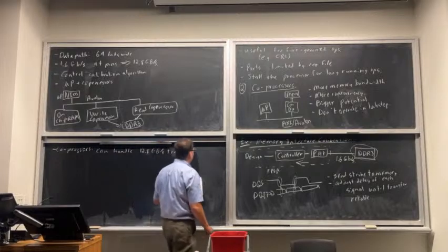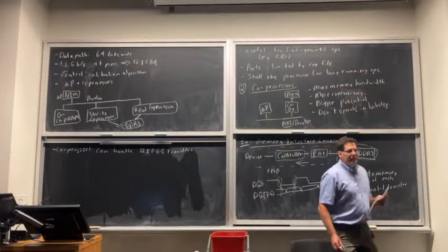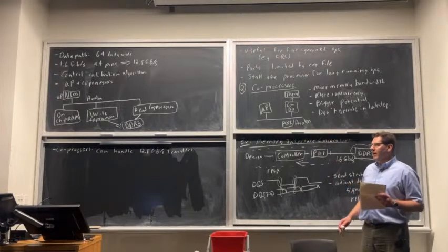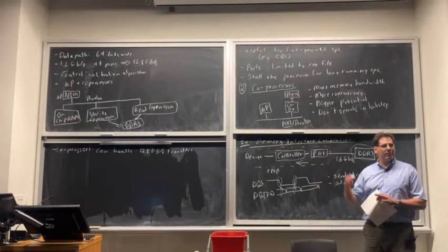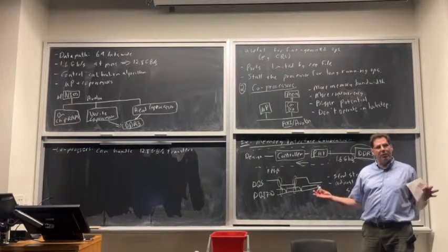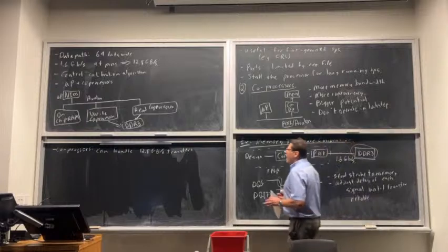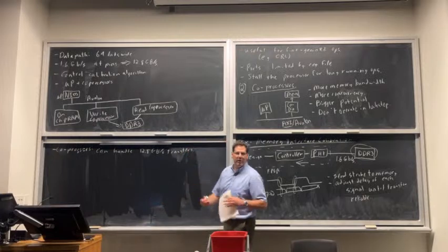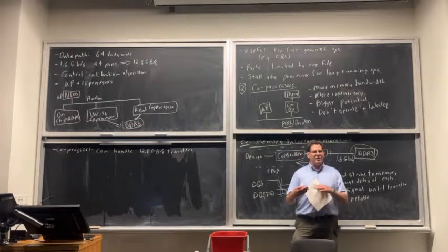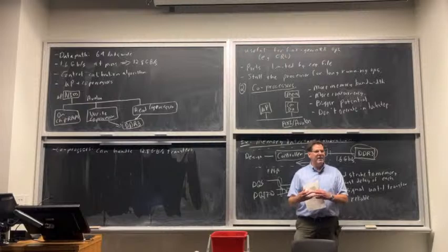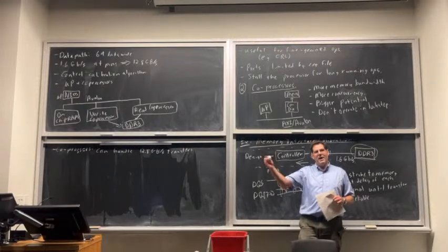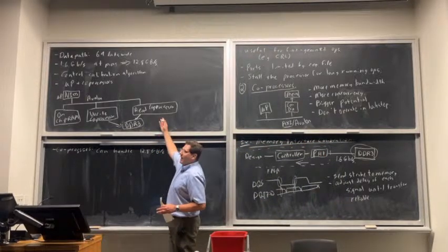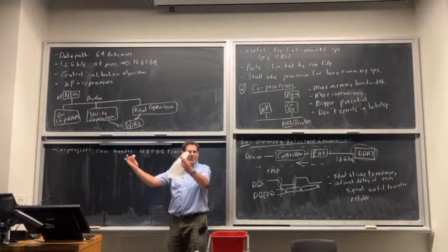Okay, so the way they did that is they run at, for example, 400 megahertz, times 256 bits wide. Okay, so they can't run at 1.6 gigahertz, but can run at 400 megahertz. Send 4 times as wide a data word, and then a little bit of logic at the very end basically muxes that together, right? With the last stages being in the IOs themselves. That's how you kind of match bandwidth here. I can't make this run fast enough, but I'll widen the data bus, and now it can send enough data.